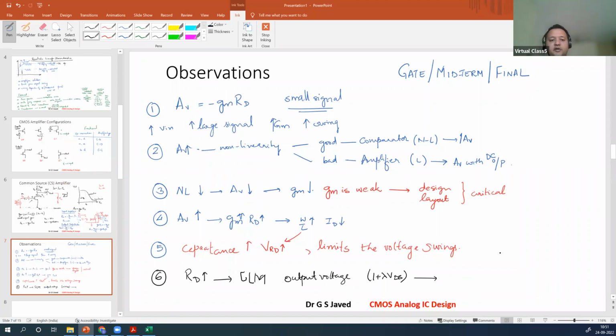So how does the gain get reduced? From Av is equal to minus gm RD, right? Because you will now form a loop there, with 1 plus RD times lambda ID, this effectively becomes Av is equal to minus gm times, and now the role of RD gets replaced by a parallel resistance of r0 and RD.